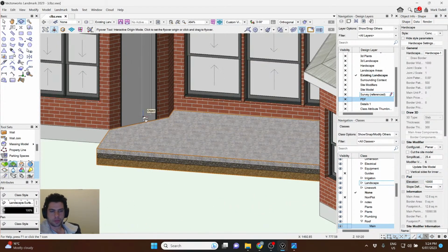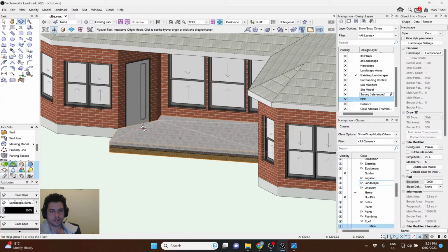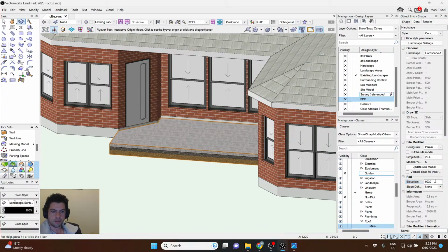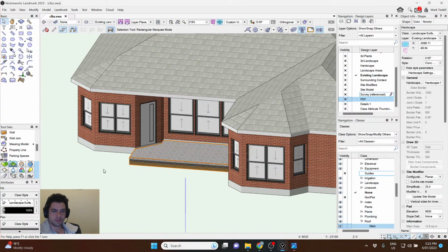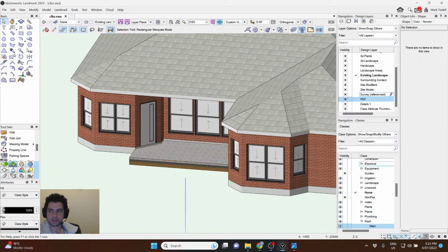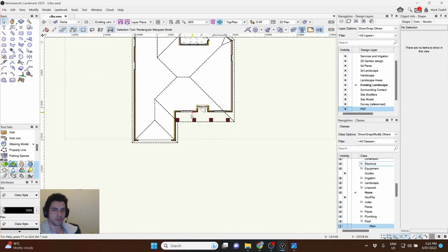But very rarely will you have a house just come straight out onto any hardscape because it's just not really done, probably to prevent water and things like that from getting back in. Most of the time I see a 70 mil step down in Australia in terms of step downs from houses to different bits. Might be different here in America. I can't really tell from the photos, but it's good enough for me to roll with.